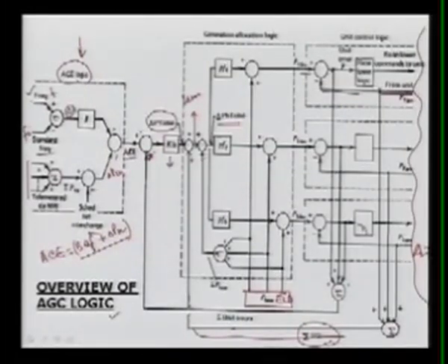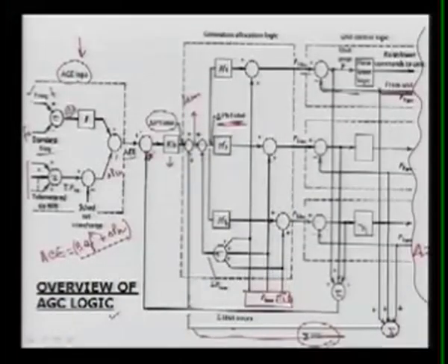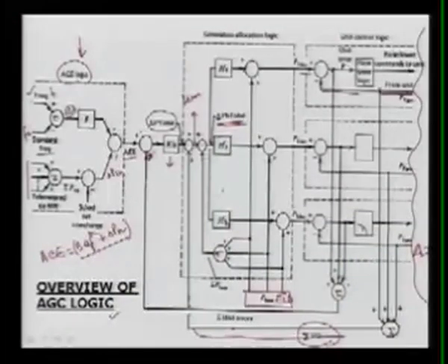So now the change in the total power in that area is distributed over the various generators from 1 to n. Again we are using the participation factor, meaning for one generator there is a PF1 value, PF2 value, PF3, and so on, and then it will be shared, and finally we get a value here, and that value is going to be added with the P base. That will give you the P desired of that unit. Means this change plus the P base